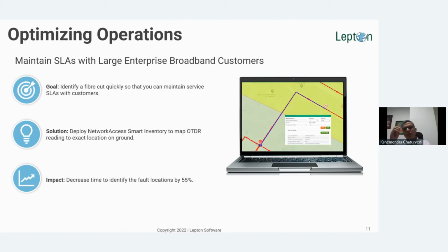There, the GIS based system comes in very handy when it integrates with your OTDR system, because the OTDR system gives just the optical distances. So it integrates with that and brings in the geospatial aspect, the accurate location. It can tell the nearby locations, the nearby manholes. It gives the precise navigation route to your field engineer, so that he can navigate to the exact location and fix it quickly. I think that comes as a greatly handy tool.